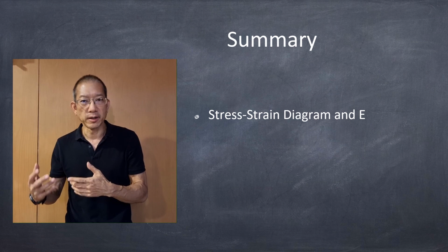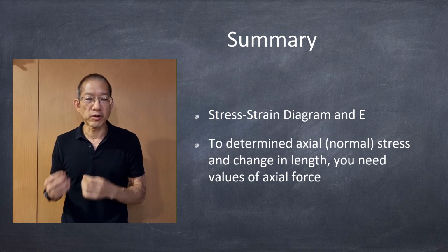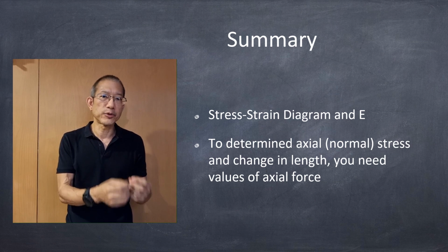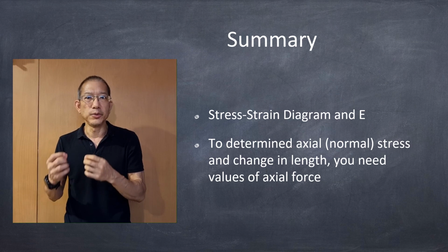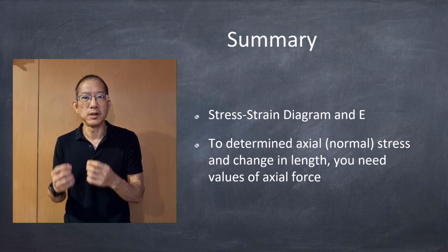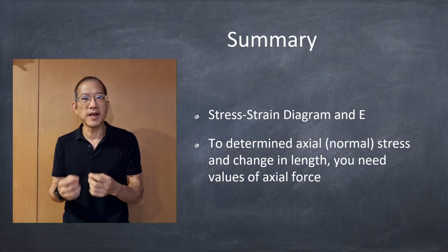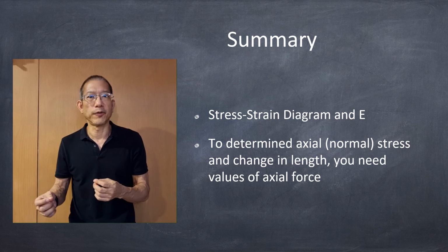The second point I'd like to make very strongly is that to calculate this type of stresses and the change in length, you need axial forces, not external forces. Internal force is caused by external force, correct?